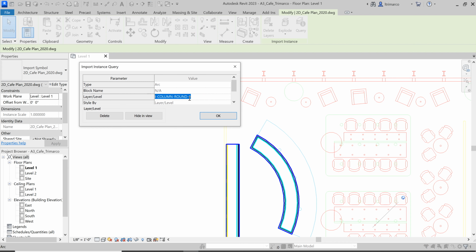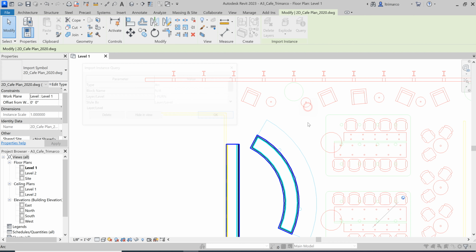And because we are using our standard layer naming convention of 2 suffixes, 3 suffixes, 4 suffixes, literally immediately I can see that this object is on a layer called I-column, and it's round and 1. So literally the first 2 suffixes tell me interior and they tell me column. So immediately I know what I'm building. Same thing for the other object, that circle there.